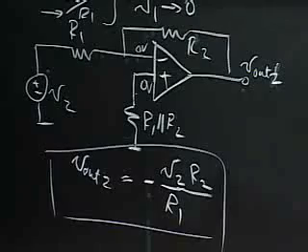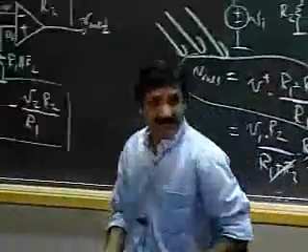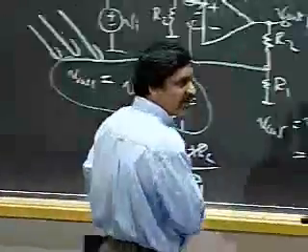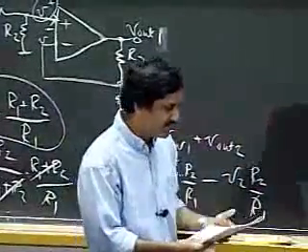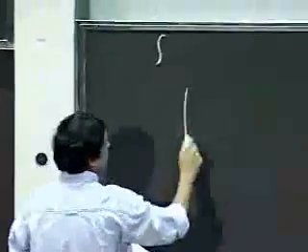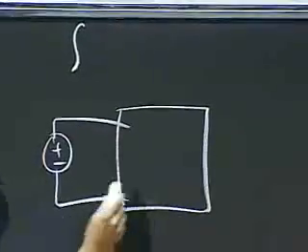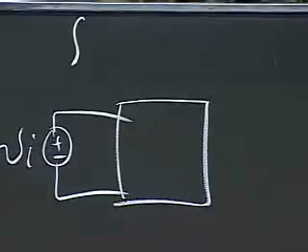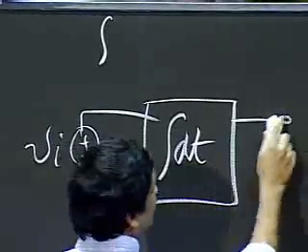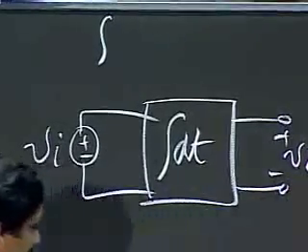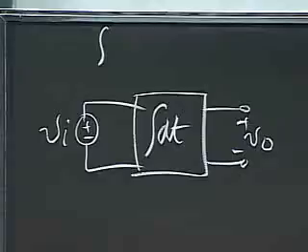We built a subtractor. And as the next step, let's go ahead and try to build an integrator. Okay? Using this little building block, we can go ahead and try to build a bunch of circuits. We can build filters, A to D converters, and so on. Let's build an integrator. Okay? So abstractly, I need to build this box. Which, when fed a VI, I want that box to integrate and give me a VO, which is VI integrated over time. That's what I want to build.